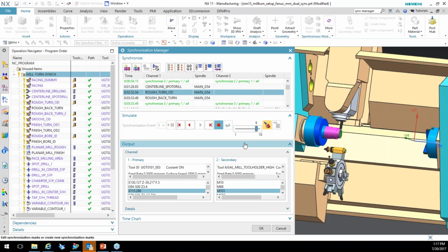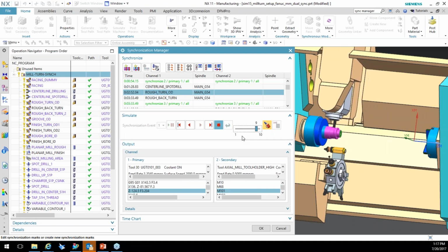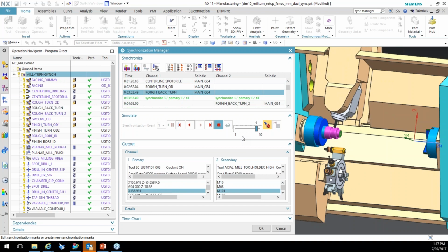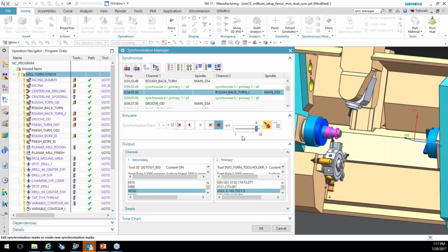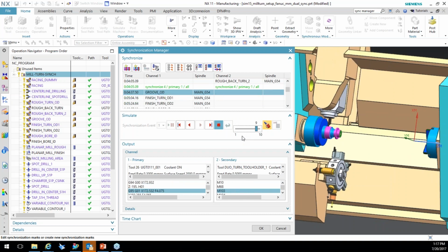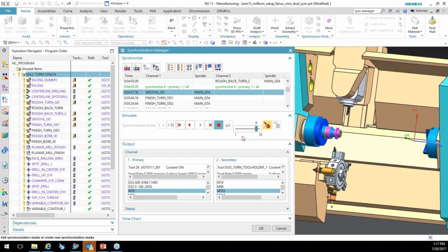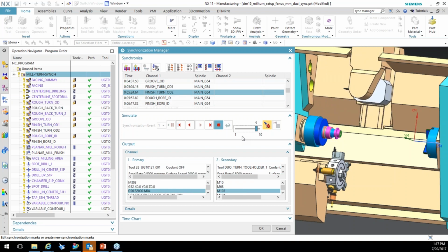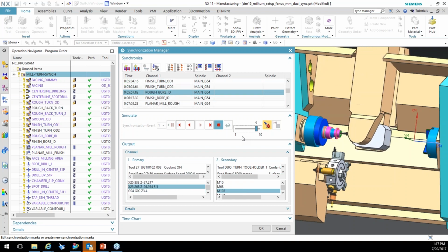And from experience, on the floor experience, I have 20 years in programming of different style CAM systems. I've been with NX for about 5 years now. And every one of your CAM systems, they're going to produce the CLSF file, and then it's going to run through a post processor. So your code is only as good as your post processor and your machine toolkit.